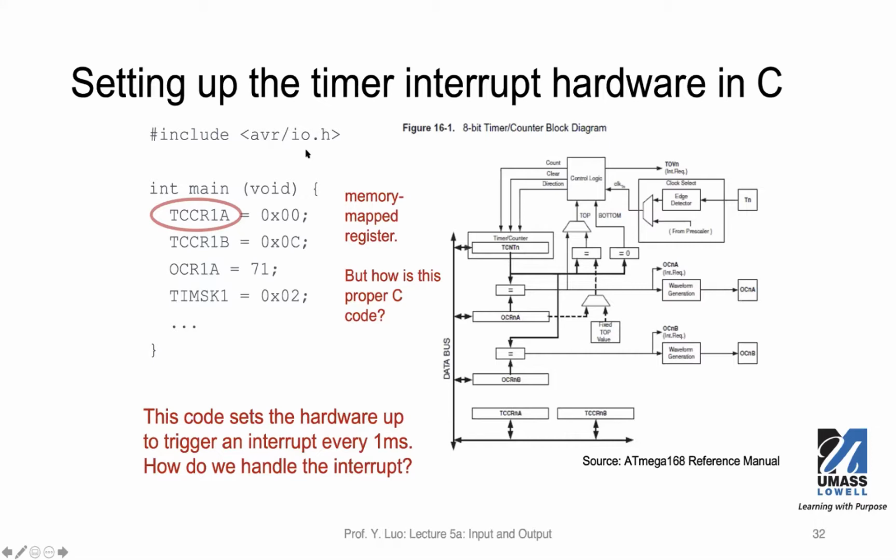When you have an SDK from a microprocessor vendor, you will have example code like this. If it is in C, it will include header files. And you will find similar lines like these ones that use register names as variables that you can refer to. These names, definitely they are defined in one of these header files.